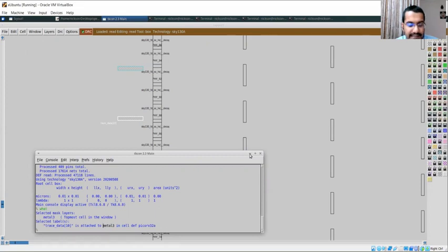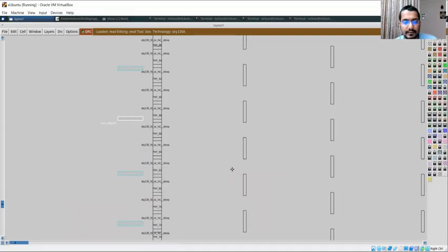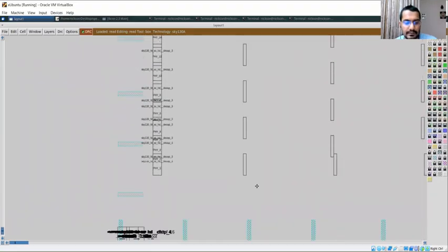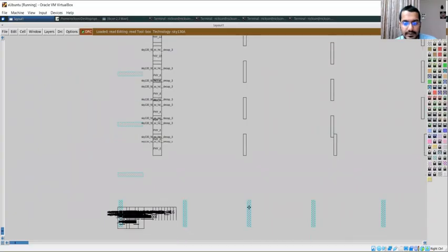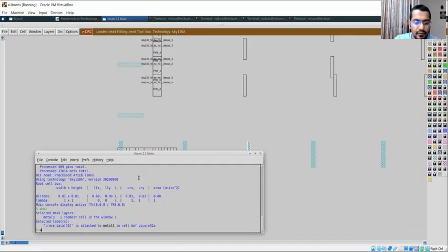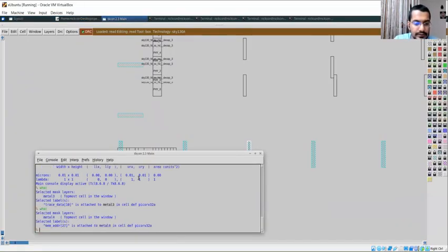So this is in metal layer 3. This is what we had set in the horizontal metal, IO horizontal metal. Similarly, when you go down, there are vertical pins. You move your cursor over the pin and do an S, and you take the tkcon window and do a what. Should be metal 4. So yes, it is in metal 4. So metal 3 and metal 4. This was what we had set.